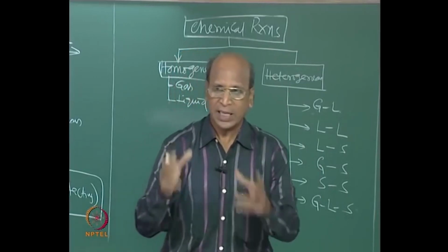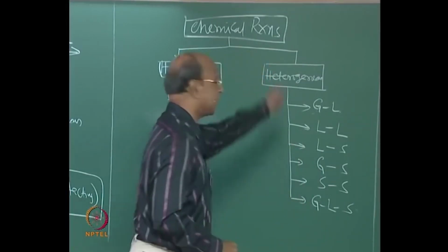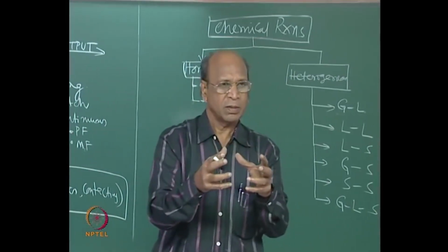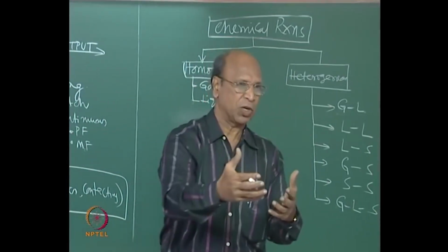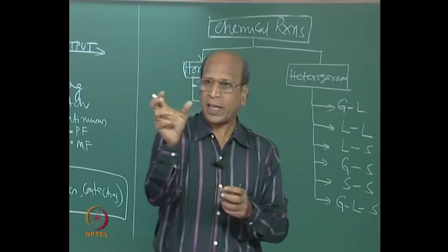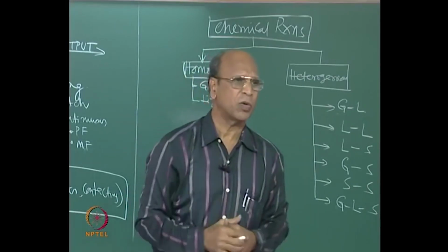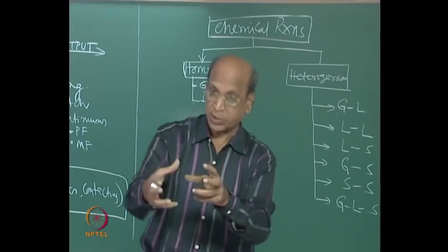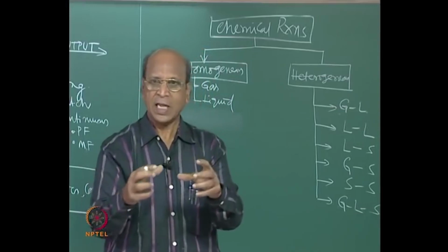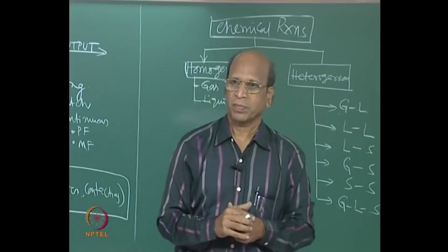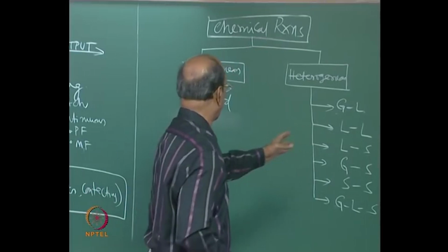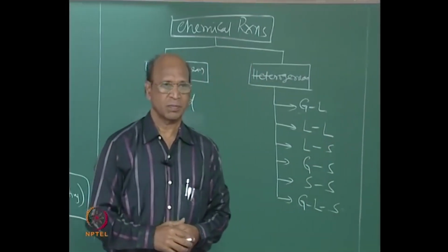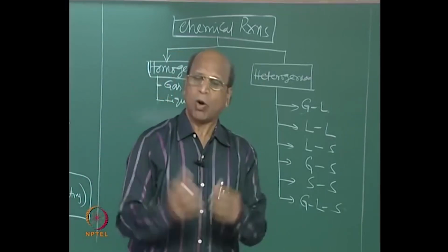Right? And now the same thing if I extend for heterogeneous systems, now this volume is there. That volume is what? Homogeneous reactions I am talking about, moles per unit time per unit volume. What is that volume? Volume of reaction mixture where both are miscible, right? If it is liquid or gas, we are talking about that volume. And now, if I take liquids that are not miscible, simplest example, then how do I express that rate?